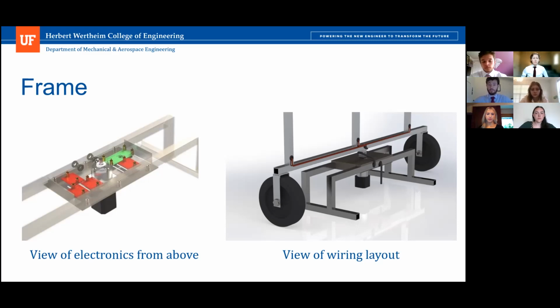And we also determined that using 26 gauge wire, the top motors need 1.7 amps, and the motor drivers we're using with a heatsink provides 2 amps. The motor drivers also provide 30 volts, which we would end up losing about half a volt with the distance of wire that we need to get up to the top motor, but the top motor is only 24 volts, so we would be fine.